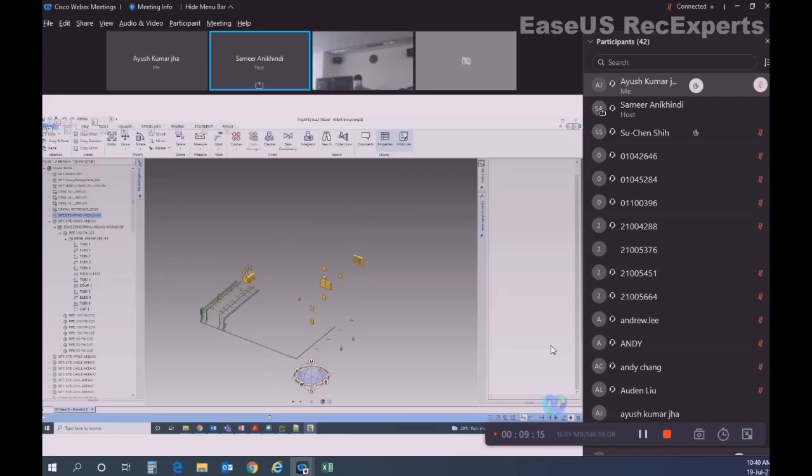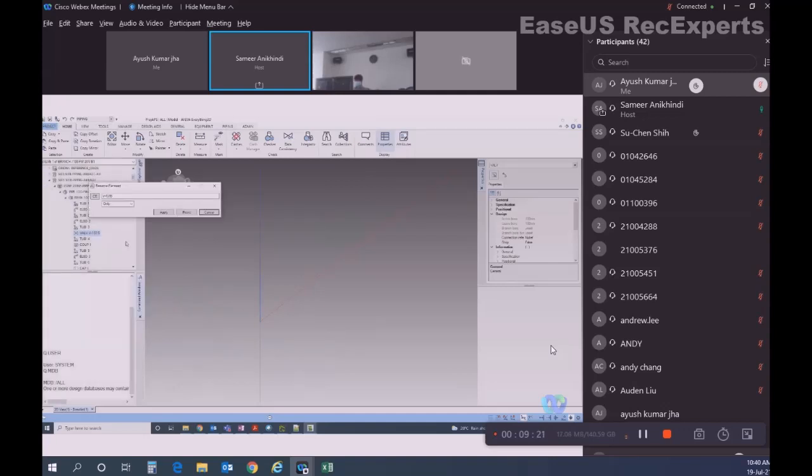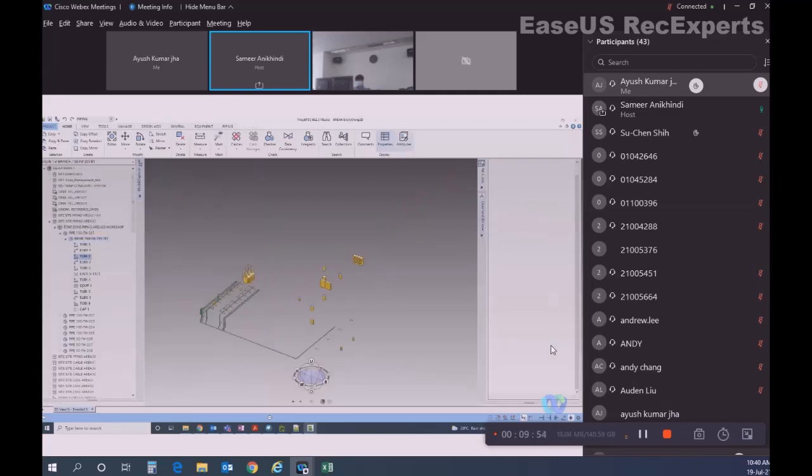Right. Now let's see, as a system user, I want to change this wall again. I'm trying to rename it and I will name it as 16. And if I press apply, see what message it gives. Unable to claim branch, element is already claimed by user Piper. Name Harish, my machine name and my login name, everything is given, and which date and what extract. So until and unless the Piper user releases this hierarchy, other users cannot change it. That means this hierarchy is bold.